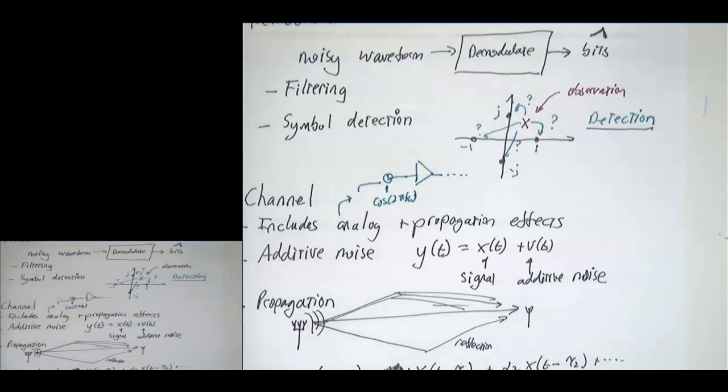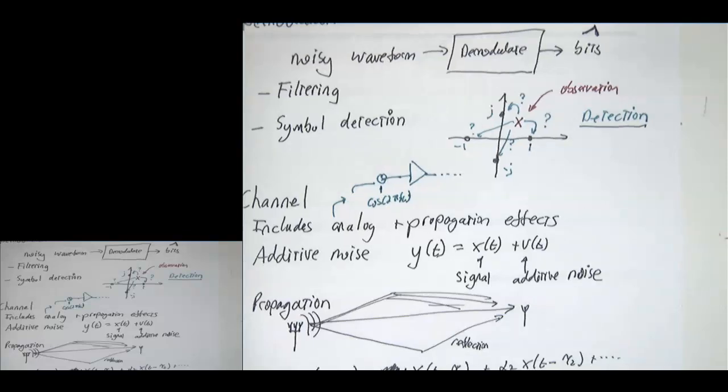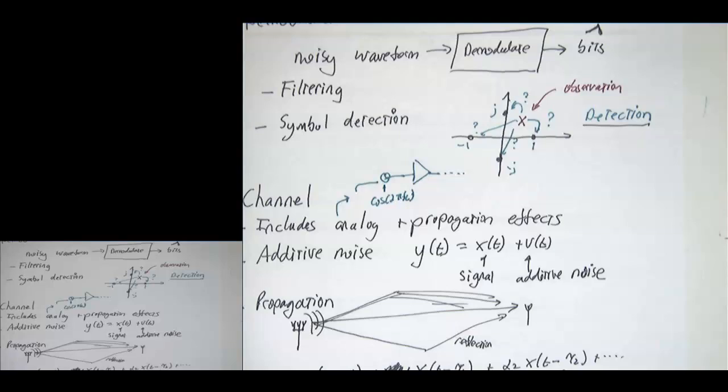And then if you study RF electronics, you find that each of these operations introduces noise. And they also introduce nonlinearities, too. So all that could also be included in here. Now, usually, we design the system such that it's as linear as possible, because dealing with nonlinearities is very hard. But in theory, all of that can be lumped into the channel. So you have phase noise, you can put it in there. Anything that's kind of non-ideal goes in that channel.